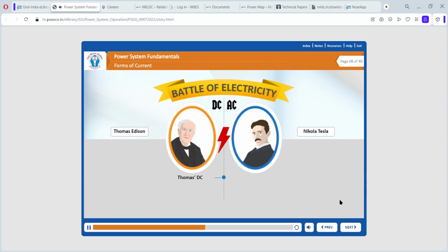In direct current, the current only flows in one direction, whereas in AC, it changes direction periodically. The frequency in a DC system is always zero. In case of an AC system, frequency varies within a band across the nominal frequency. Nominal frequency is different for different countries. Like, India and the European electric grid follow a 50 Hz system, while the USA follows a 60 Hz system.